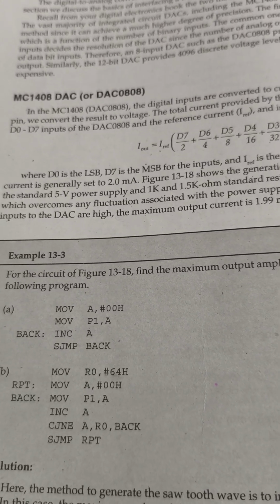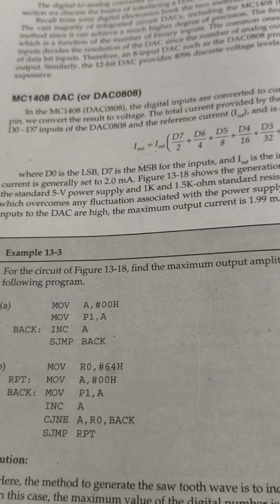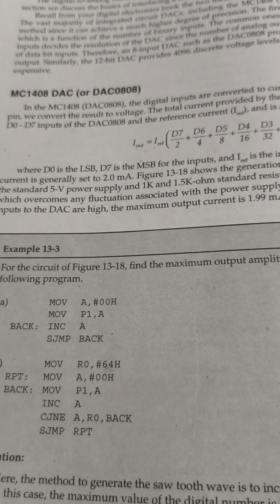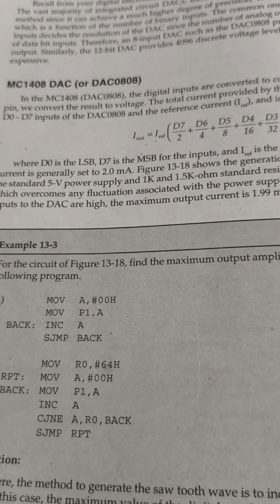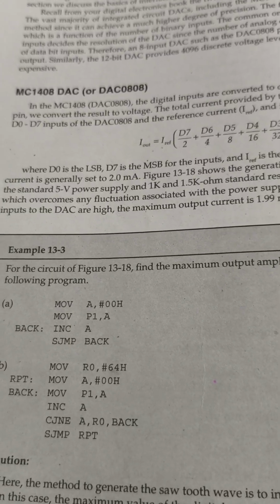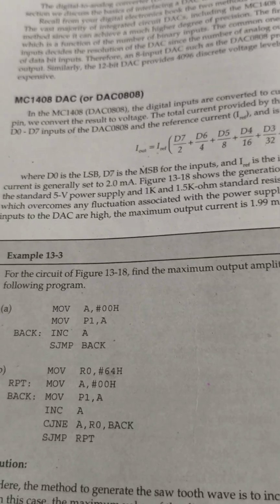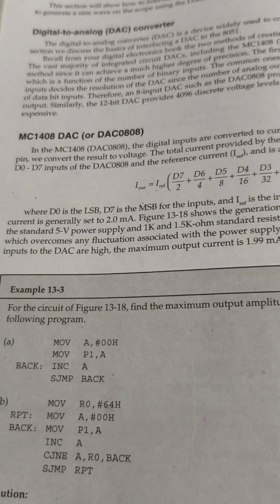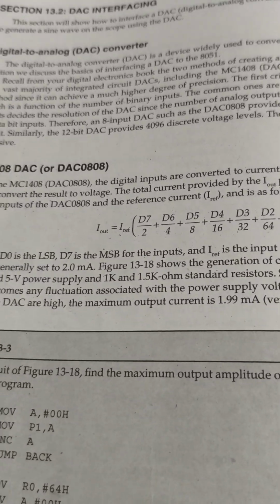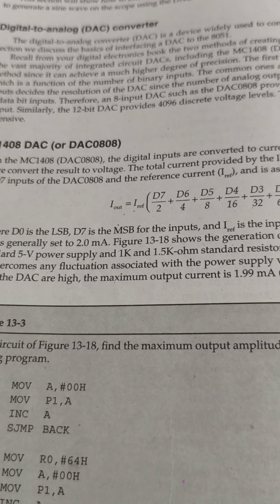If voltage exceeds, for example, 230 volt, automatically stop the induction motor. If current exceeds, for example, 5 ampere, then automatically stop the induction motor. All those control activities will be done with the help of the 8051 microcontroller.